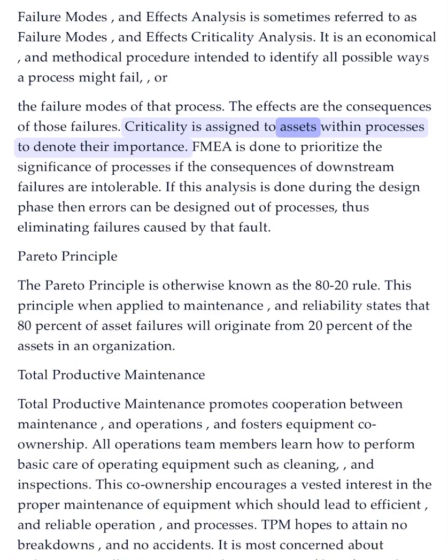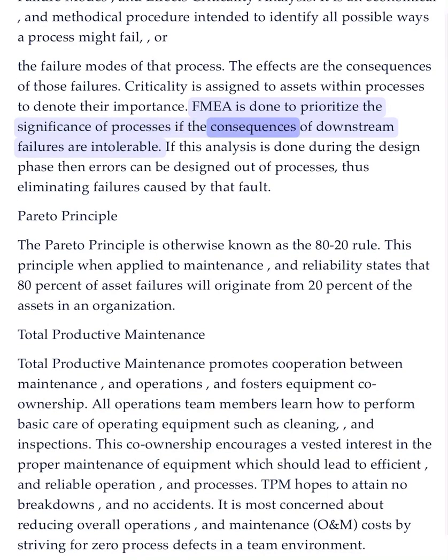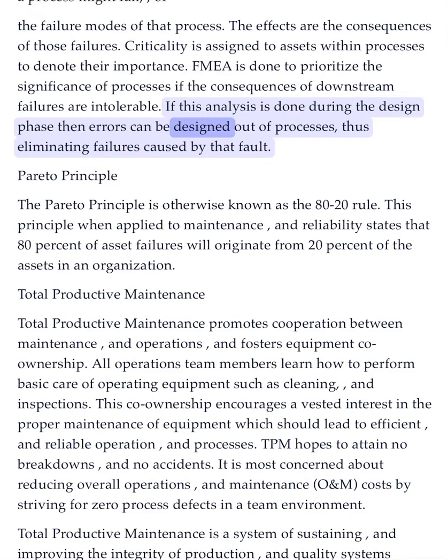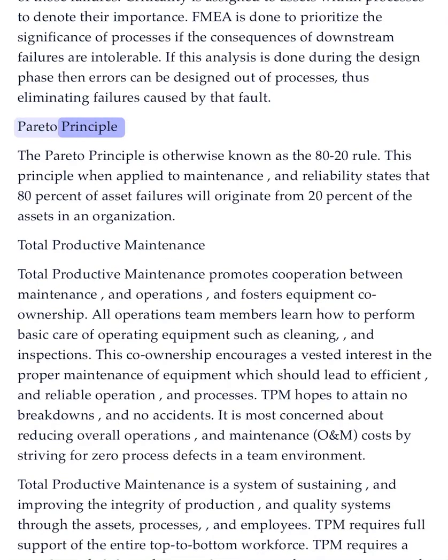Criticality is assigned to assets within processes to denote their importance. FMEA is done to prioritize the significance of processes if the consequences of downstream failures are intolerable. If this analysis is done during the design phase, then errors can be designed out of processes, thus eliminating failures caused by that fault.